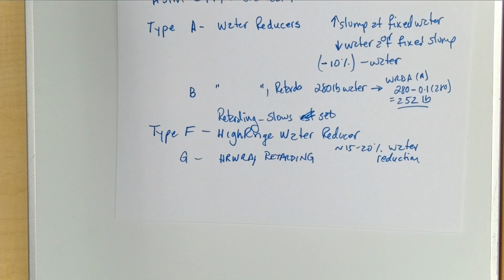And the reason that we say we shouldn't have concrete, except in a museum, that doesn't have these materials is because water reduction means we can use less cement. Pozzolans, most of which are waste, you'll notice, are garbage from someone else's projects. Although silica fume is the only material we ever kept track of per pound, we would put those materials in because we're going to get more out of our cement. The admixture lets us get more out of our cement.